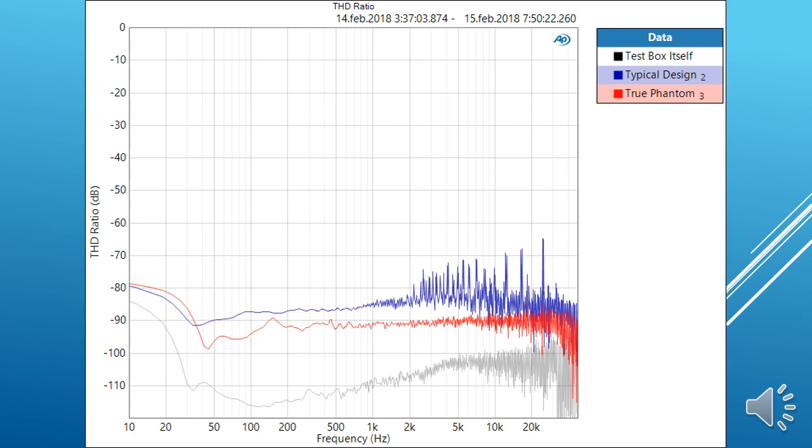But even if you discount this, there is still lower noise. And this is 10 dB differences in here. So we're still talking several dB of lower noise on a bin-by-bin basis. So the noise floor in general is about 9 dB lower, but it is somewhat dependent upon where you're at in the frequency range.